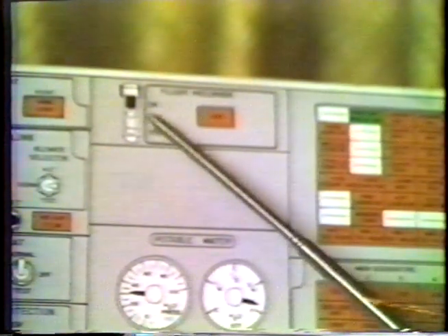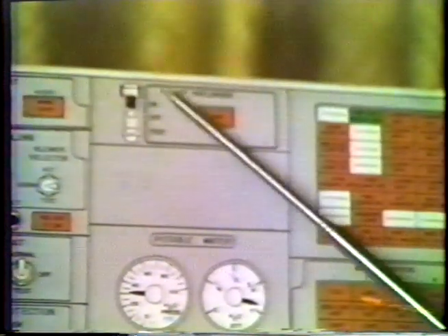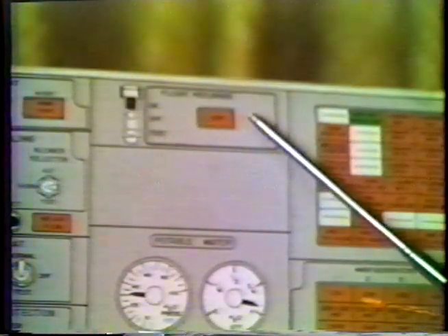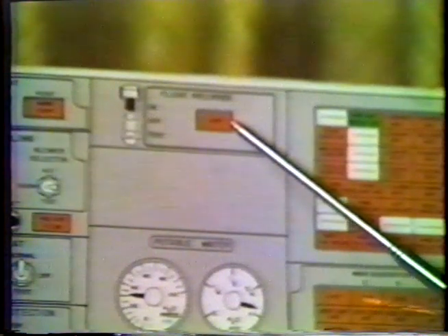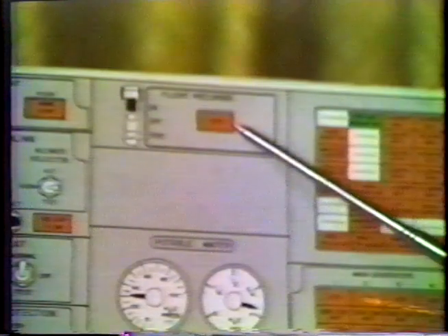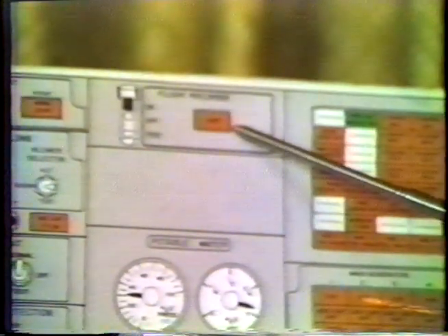The flight recorder is normally in the off position with the switch. The guard is picked up and the switch moved to the on position to load the flight recorder data. Once that is complete, the switch is turned off and the light comes back on, and the light will automatically go out when you go to aircraft generators, and the flight recorder is active anytime the generators are on the aircraft buses.